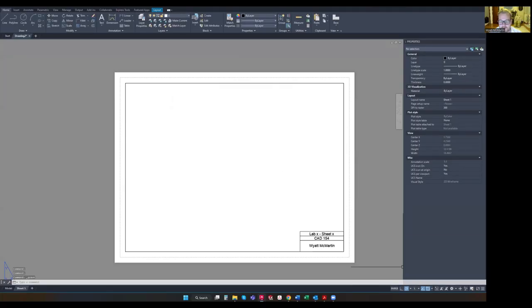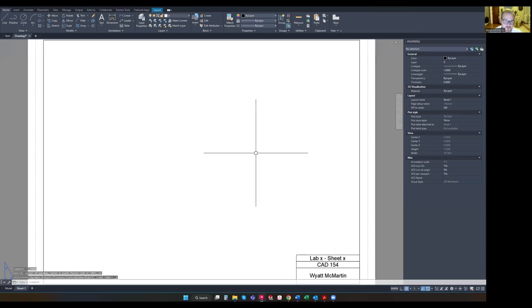So when you're inside your viewport, make sure it says 1:1. Make sure this is locked. Click out of the viewport. And everything is set up. So when you're outside your viewport, double click the middle mouse wheel, and now it'll zoom you in.